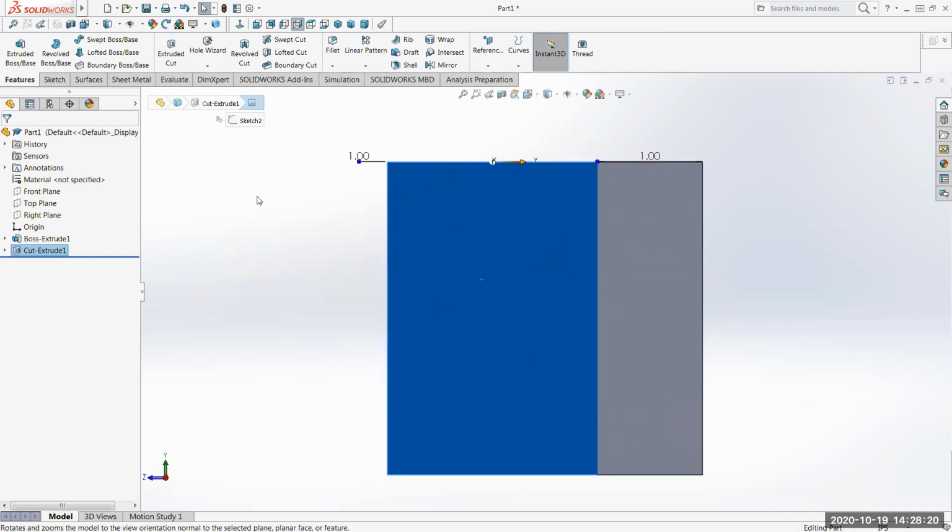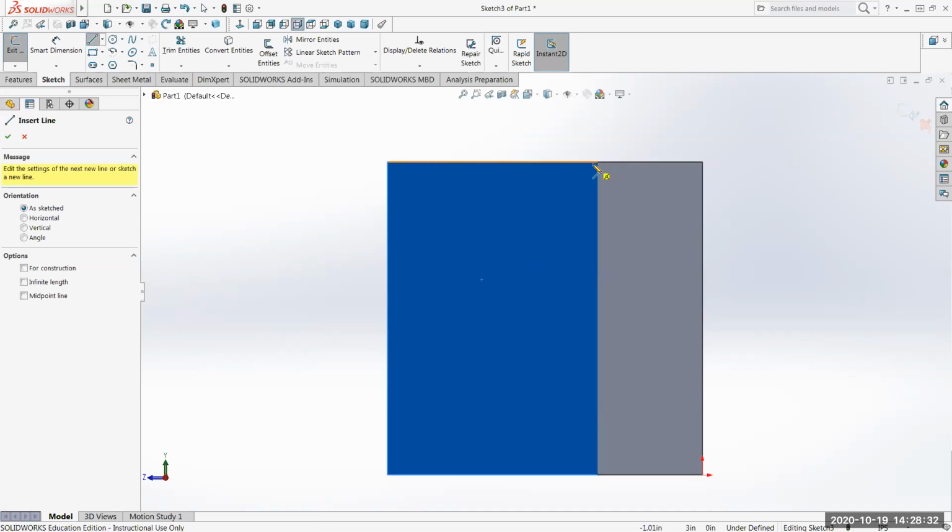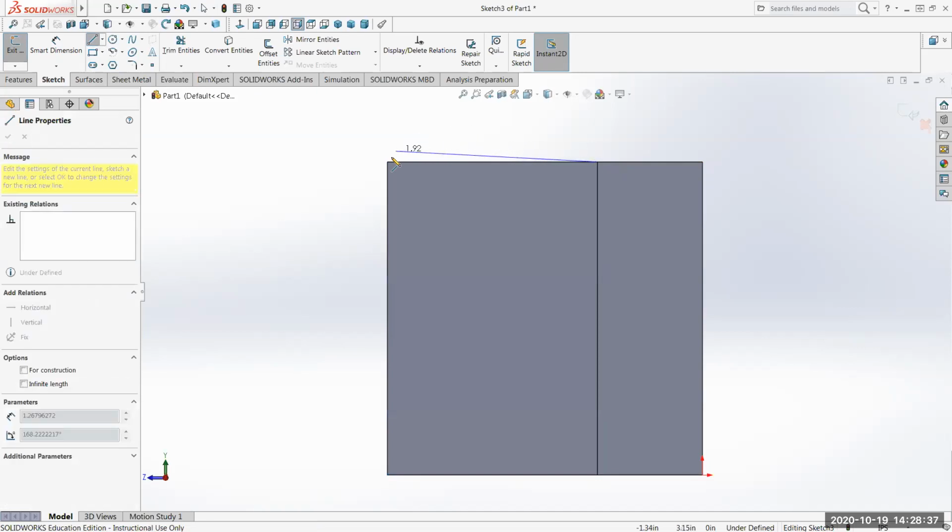So I've already selected the surface, the plane, that's step 1. Number 2 is to create the sketch. So I go sketch. 3 is I'm going to use a line and I'm going to create a full triangle. I'm going to go from this corner over to this corner, down somewhere right in here, and then back up to the corner. So I've created a full triangular entity there. Okay. So that was creating the sketch.